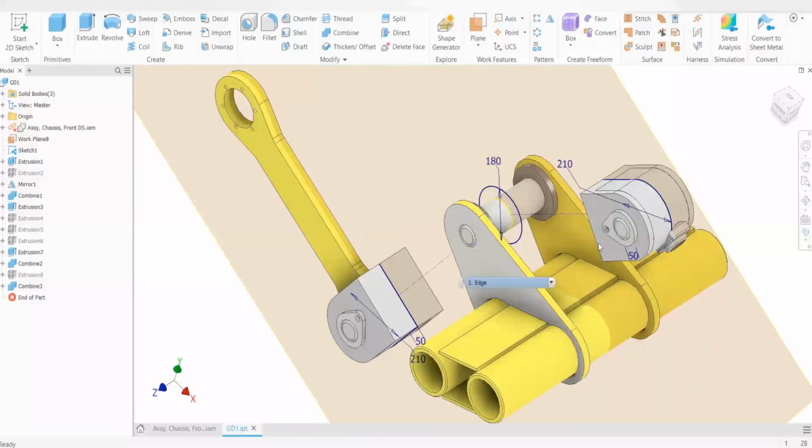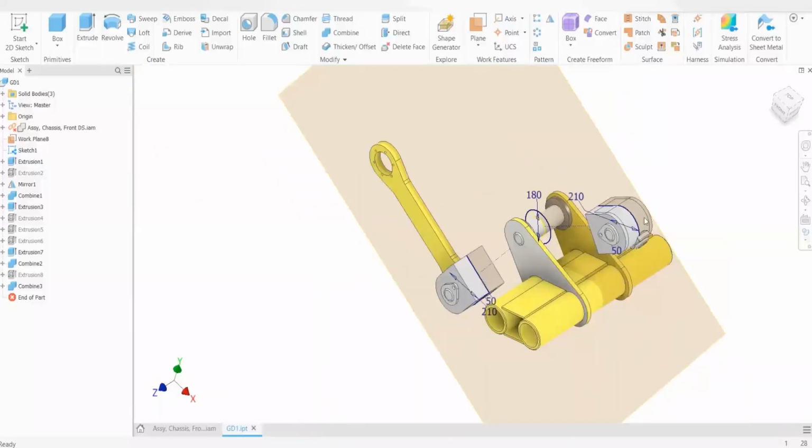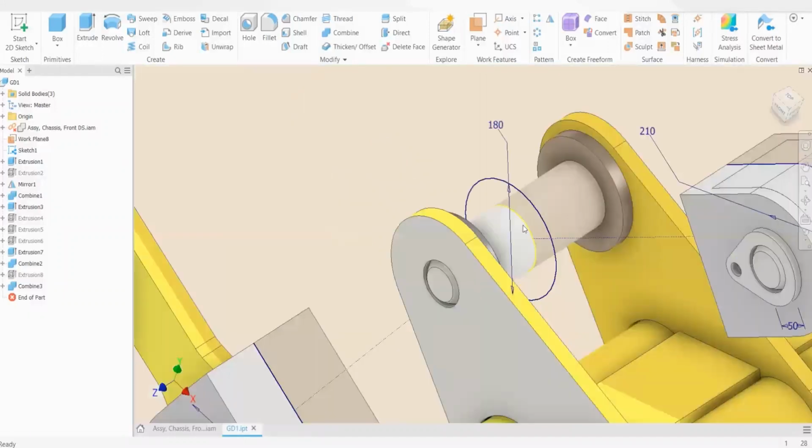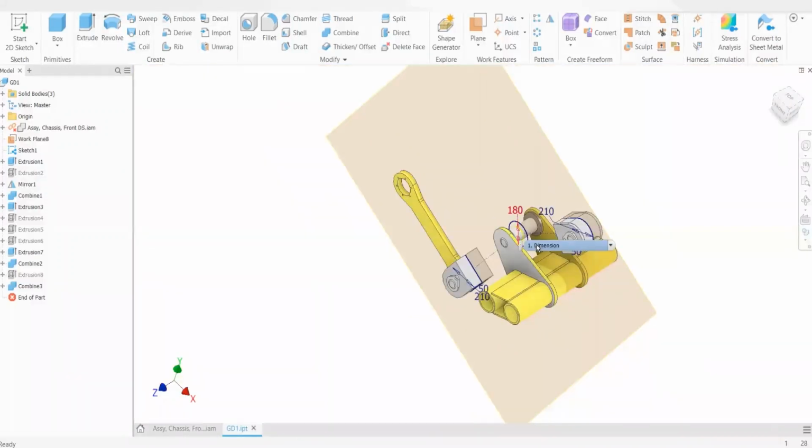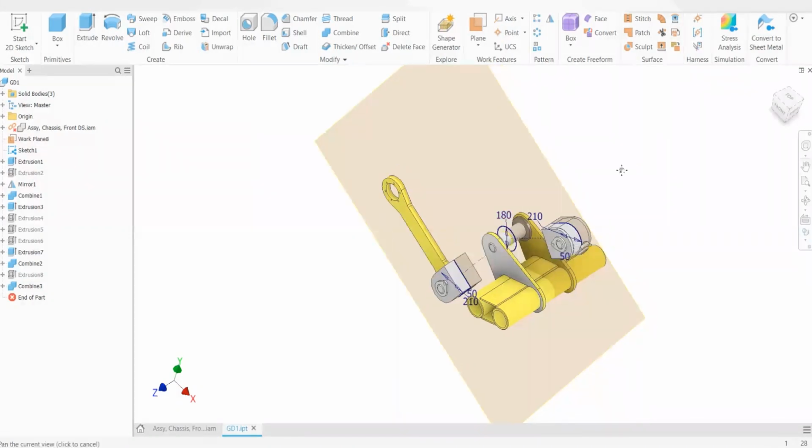So in this components, I have already created obstacle geometry at this top link over here. Okay, those solid bodies will highlight blue, and over here at the bottom. So all we're missing now is the preserved geometry that the arm will fit around at the center of this pivot point. Now at this stage, we want to get this information into Fusion 360 so we can start the generative design process.